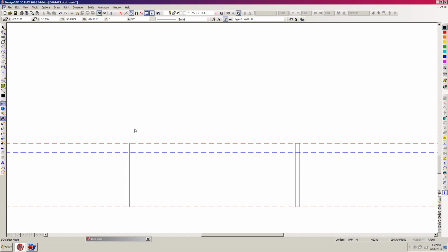Now I'm going to draw my ceiling line by right-clicking at this upper left wall point, and first I hit V for vector, and right-click so it gravity snaps and sets a point. Then I'm going to go over to this far right and right-click, and you can see I have my line already set and ready to go, so I can either hit enter or hit my scroll button on the mouse, and it's created my ceiling line across there.